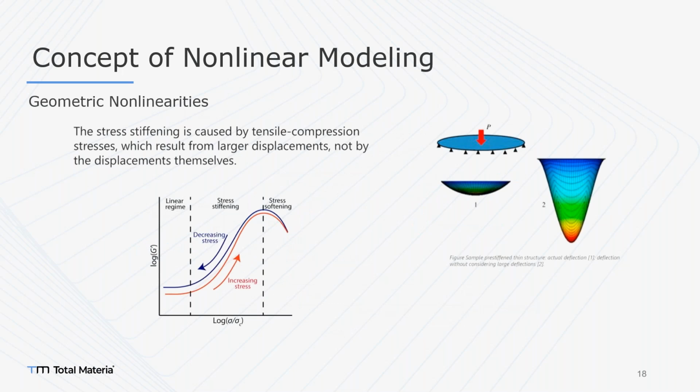So what I've got here is the geometric nonlinearity. This is a very common example of nonlinear geometric behavior. As you can see, there is a membrane in here. Membrane means there is no rotational degree of freedom on that. It's like a cloth. You can assume that it's a cloth and you just clip it in here with the whole boundary. So you have a payload and the nodal force in here.